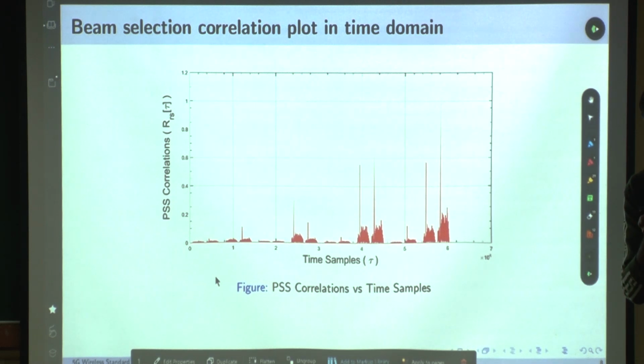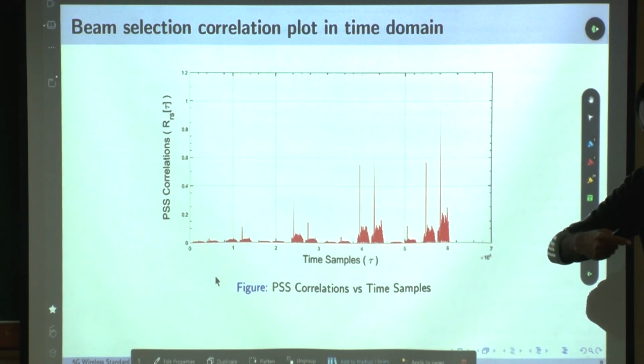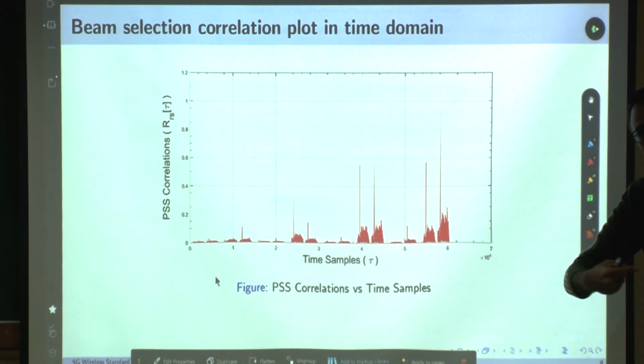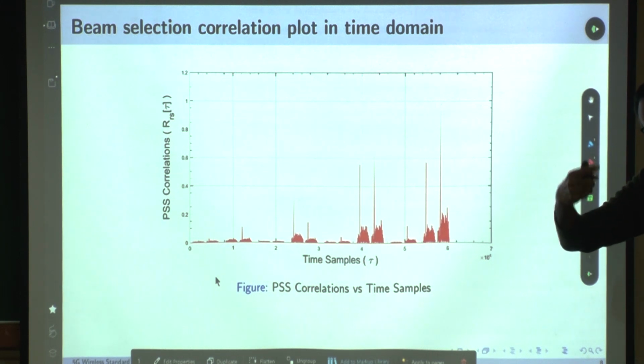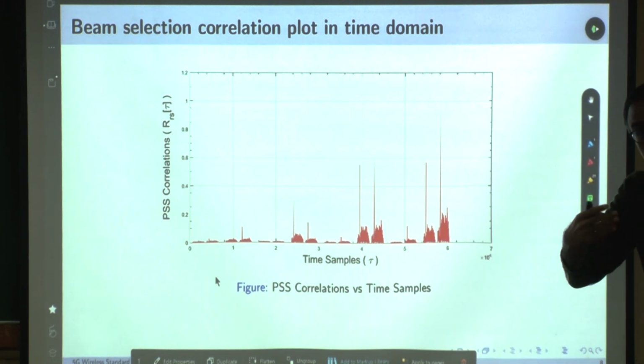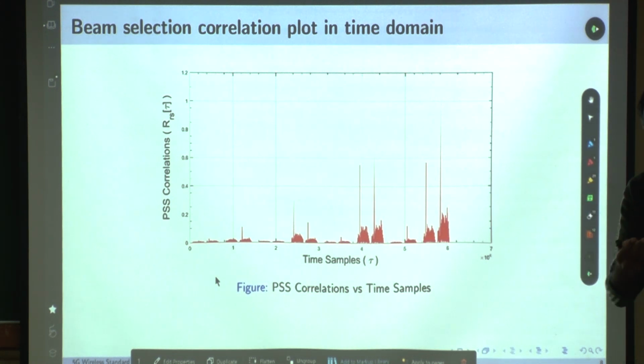Base station will basically transmit in a particular direction. What will the user do? The user will use 4 different receive combining vectors in 4 different directions. Then the base station changes its beam, and the user again does it 4 times, then a third time and a 4th time. So how many such operations do the base station and user have to do? 16 times, right? Okay, fine.